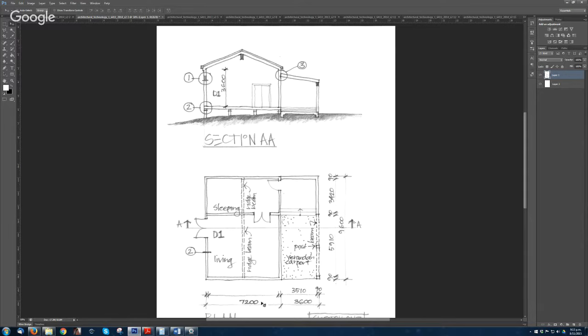We already calculated before, it was 3.6, the length of that rafter. So you divide that again by 2, it's going to be 1.8. And because it also carries the rafter on that side, you have to add another 1.8. So total is going to be 3.6. That's the load that the ridge beam is carrying.